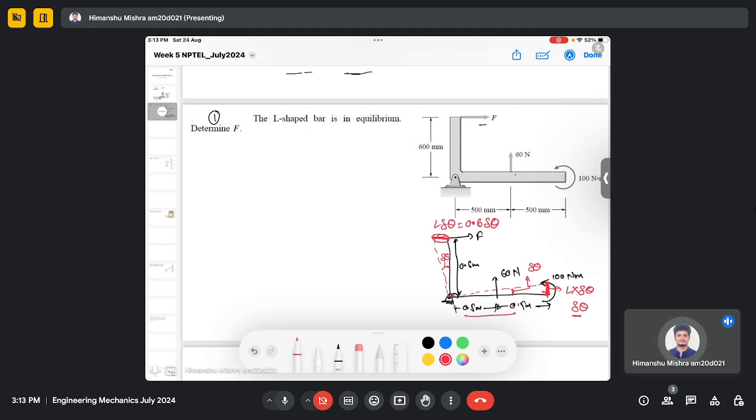Similarly, if you want to find the displacement here, it will be L del theta, which is 0.5 del theta. Here we need to find the displacement because there is a force of 60 Newton acting at that point. So we need to find the virtual displacement at that point. You can also observe that all the displacements are in the direction of the forces, which means all these forces and this moment will create virtual work. These are the forces we need to consider when we are writing down the virtual work equation.